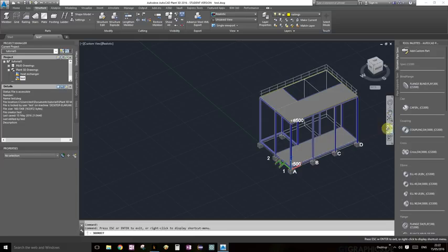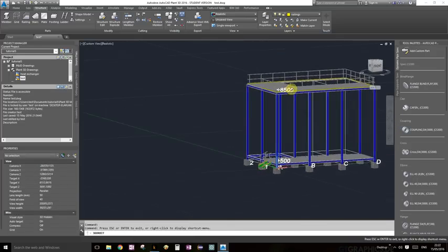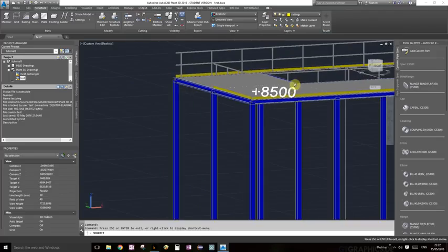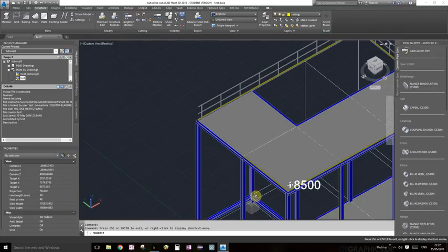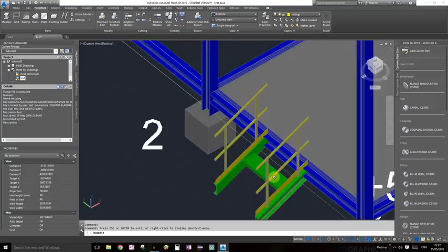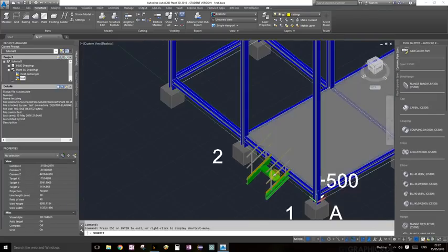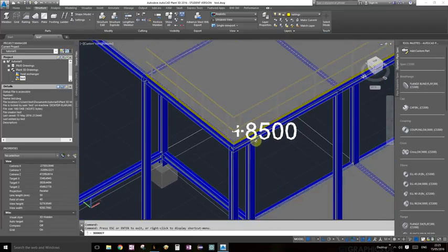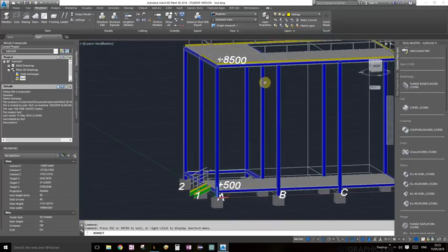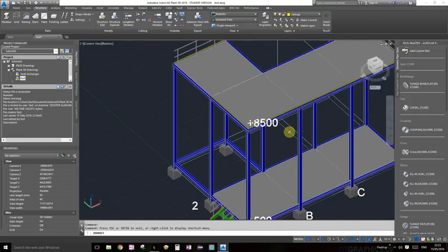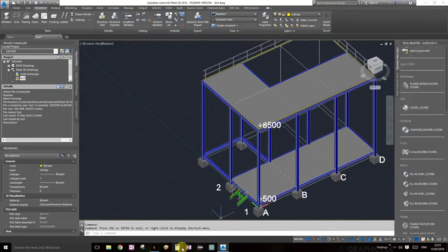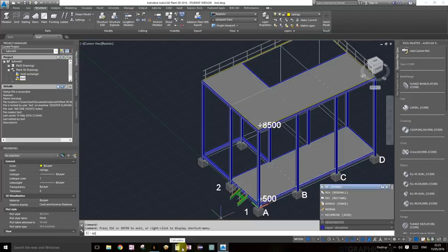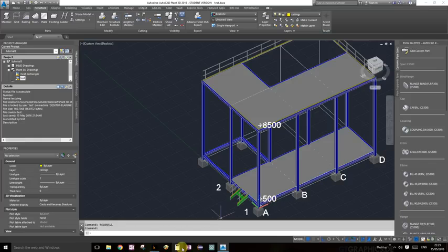Okay, so currently we have our railing. Actually looks pretty cool. One thing I'm not sure about, oh okay, it just looks gray, it's not actually gray, it's because of the lines. Anytime something is not showing up right in your model space, all you can do is start typing regen and then choose regen all. Sometimes you'll fix the problem, sometimes it might not.